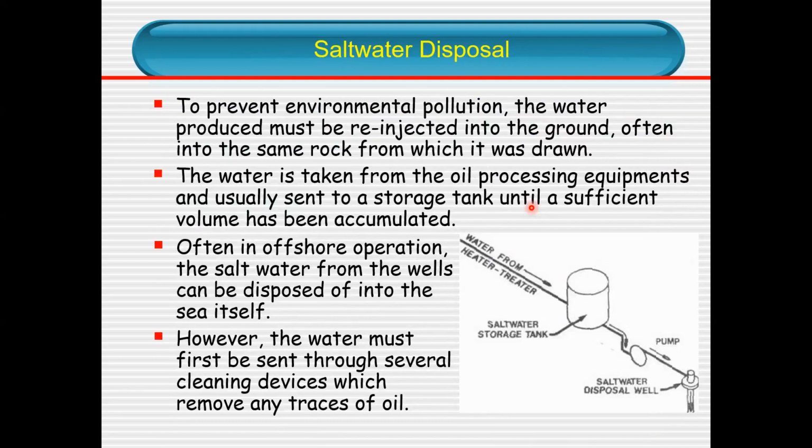Before you even sell the crude oil to the sales point, to prevent environmental pollution, the water produced must be re-injected into the ground, often into the same rock from which it is drawn. The water sometimes is not possible to be thrown overboard to the sea. So you treat it, and you re-inject it back to the same well or to another well. But it must be treated because untreated salt water can cause solids deposition in the formation.